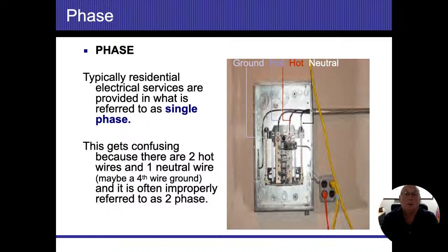One of the other things, too, when you open up the door to the panel, if you see two breakers tied together, so a 240 breaker, then that's another good clue that you have a single-phase 120-240 system. If you open up that door and you see three breakers tied together, and this is going to be either on condo buildings or big, large homes, those are three-phase systems. We're going to stay out of those.